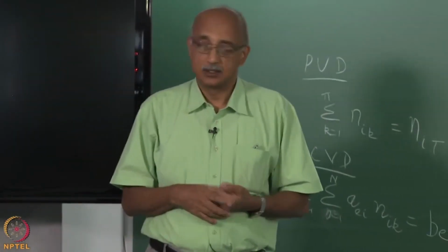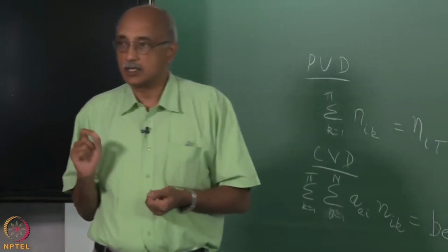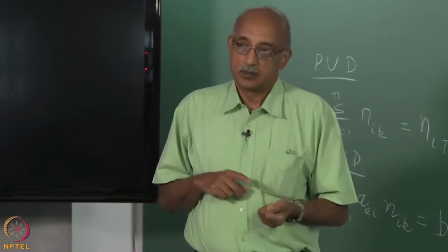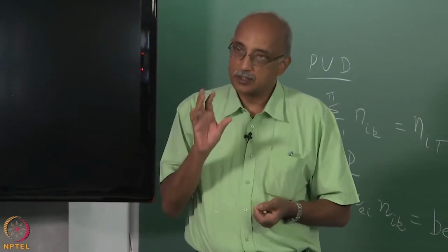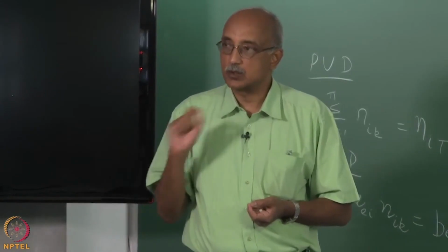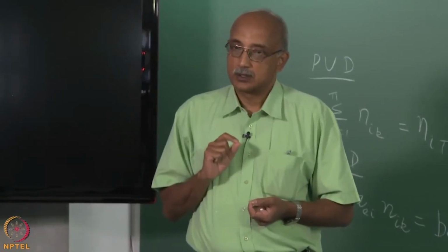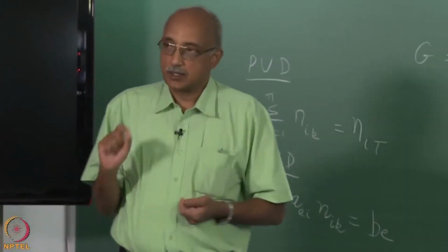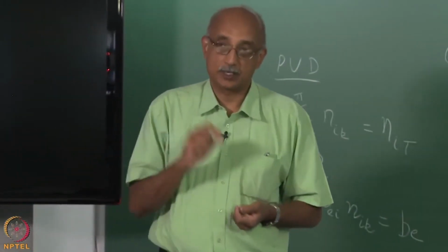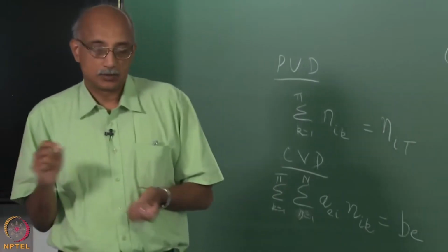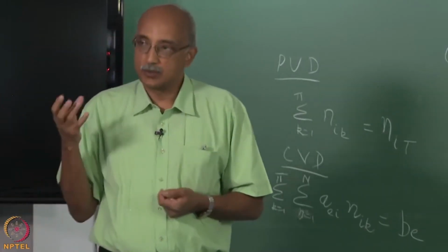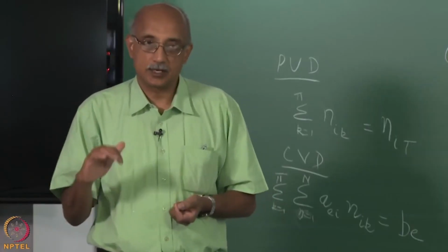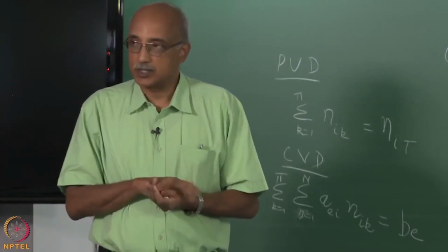Once you feed that in, at each location inside the CVD reactor, the free energy minimization algorithms will yield the equilibrium compositions prevailing under the local conditions. Now, if the program is running correctly and your reactor has been designed properly, through the entire reactor you should only see gas phase species, and the second phase should only start appearing at the substrate.